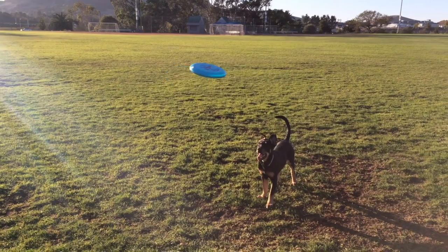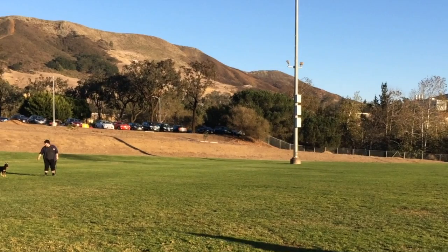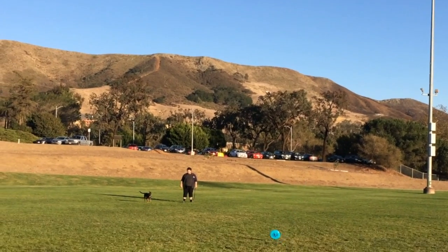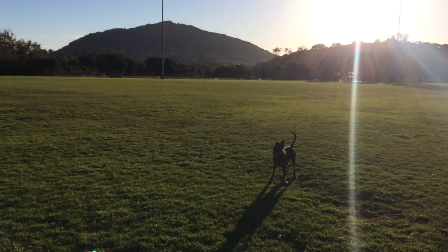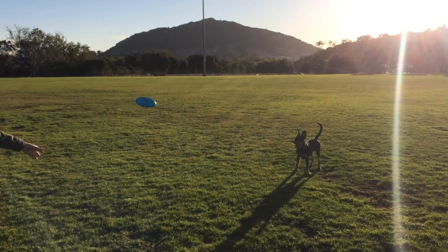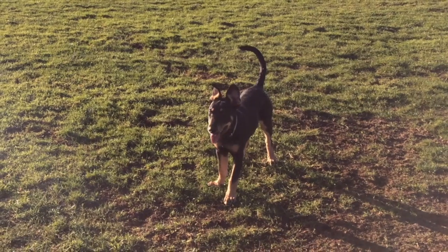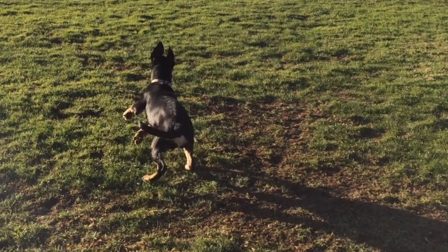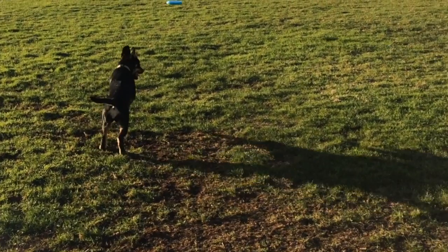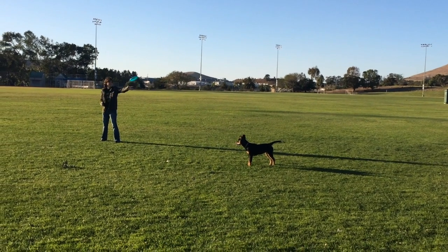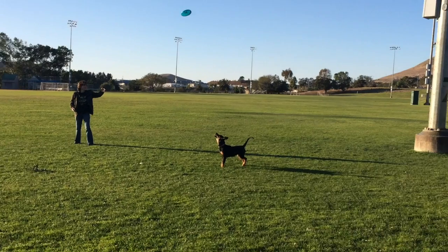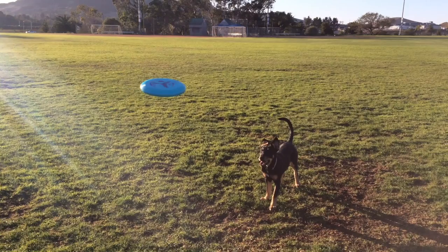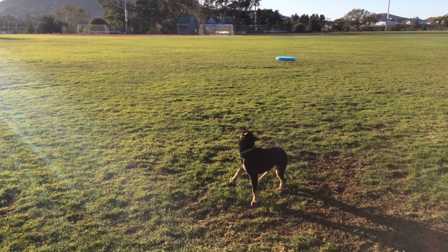When the frisbee is high up, Cassie, if motivated, will remain in the same place while always seeking to keep her line of sight directly in line with the frisbee line. In other words, Cassie always tries to make theta dog frizz equal to 0. Sometimes this requires Cassie's head to rotate dramatically, increasing theta head bod to an uncomfortably large angle. There are a range of comfortable angles for theta head bod to fall into, but if theta head bod begins to approach the limit of this range, Cassie will reorient her body until she is comfortable again, enabling her to keep her line of sight pointed towards the frisbee.